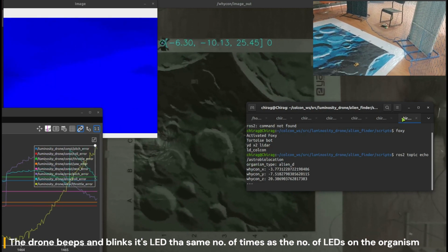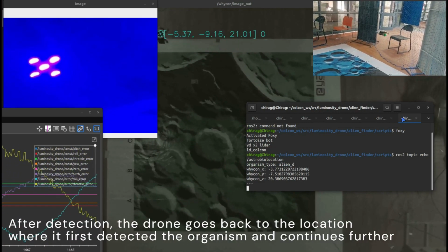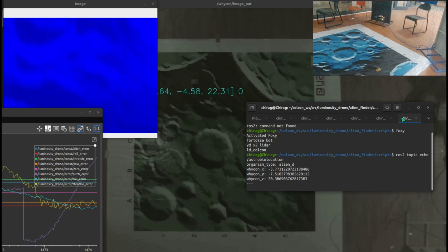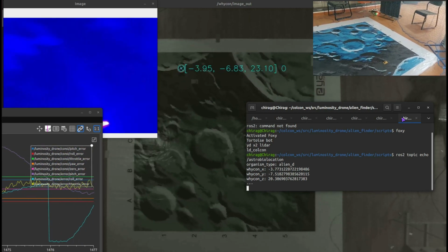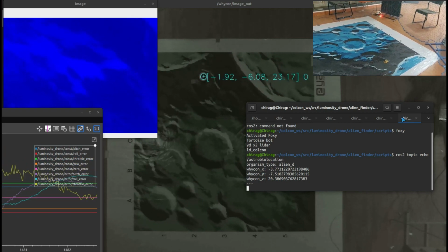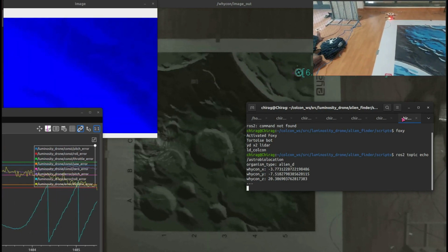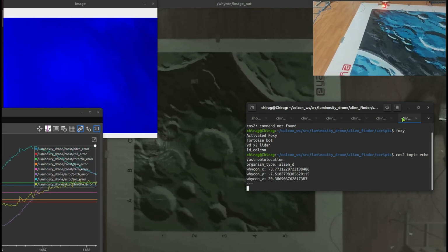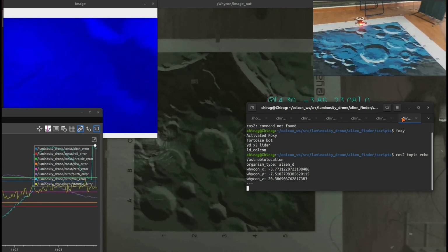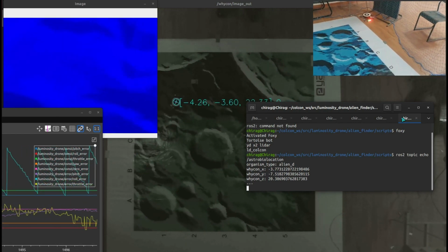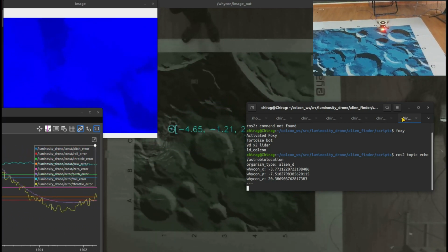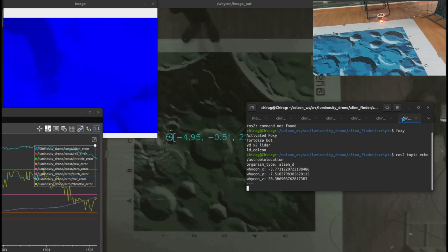As I had mentioned earlier, we faced many practical challenges while implementing this. One of them was the spikes in the change in error which we used to calculate D in the PID. This was caused due to noise in the IMU's data which we tackled using a Butterworth filter. The second issue which we faced was due to the constant discharge of the battery, the throttle base value would change throughout the run. To tackle this, we implemented an algorithm which automatically, using the flight characteristics of the drone, would set throttle such that it always compensates for the reduction in the battery voltage.